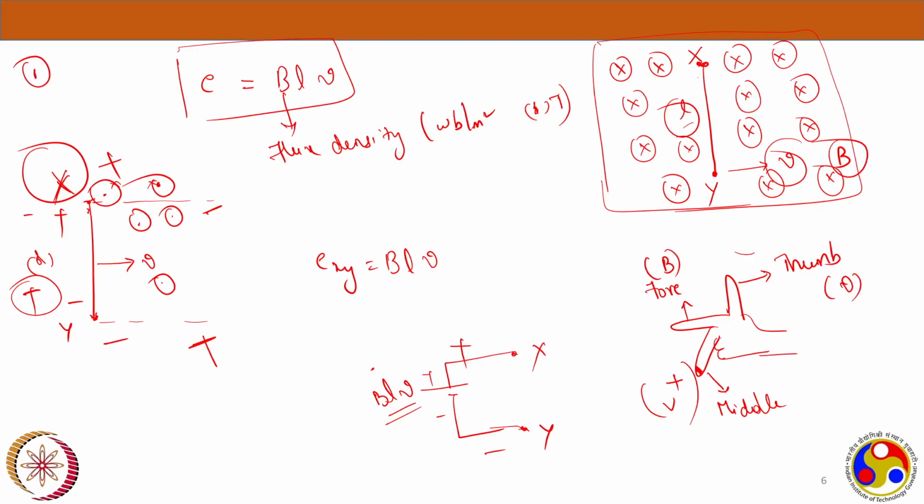So this is very important. The direction in which you have applied the magnetic field and the direction in which you are moving the coil should always be mutually perpendicular. You can't give a magnetic field and also move the conductor in the same direction. In that case there is no voltage induced. Voltage can't be generated in that condition.